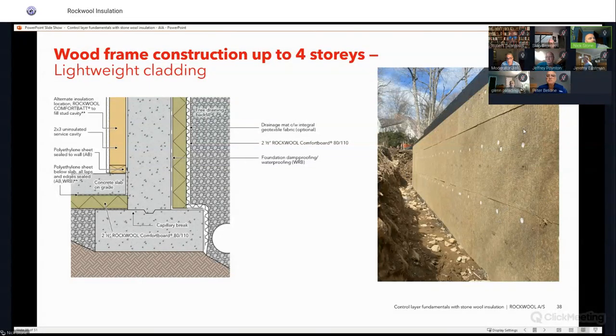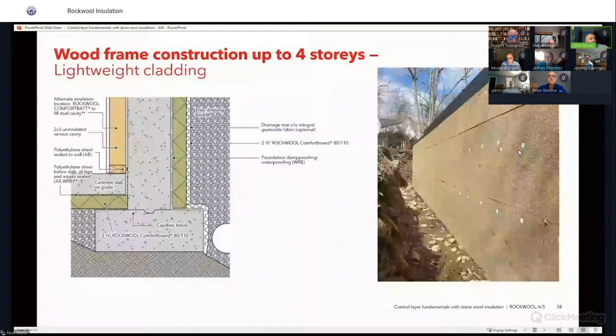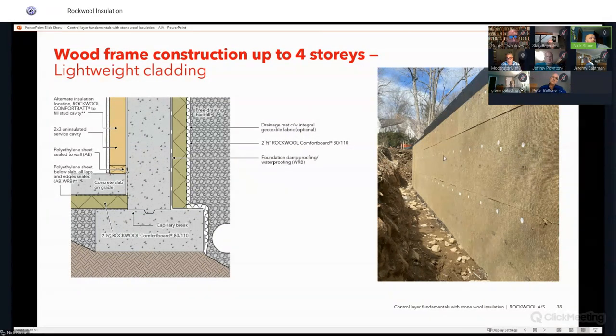As far as from a holding standpoint, the backfill is really going to be what holds all these panels in place. So no need to go crazy on putting 1,000 pins in this. Just want to make sure there's enough hold, depending upon how big the sheet is and all that, to have enough holding power so we can get that backfill in there and get that pressure up against the material, and kind of keep it in place.